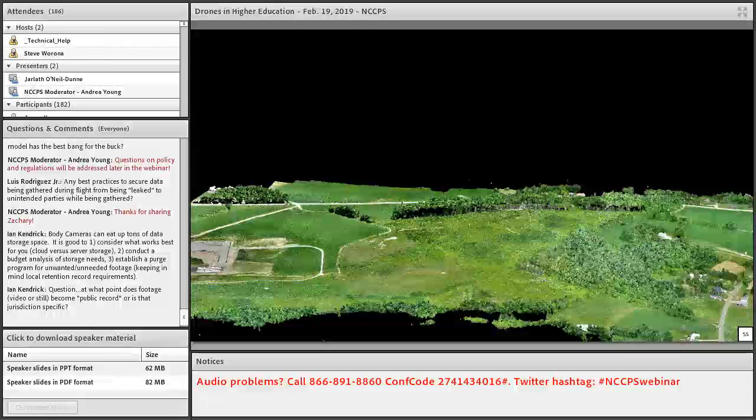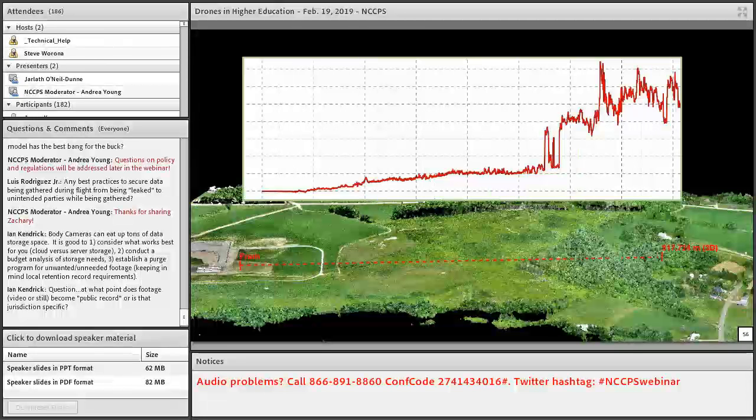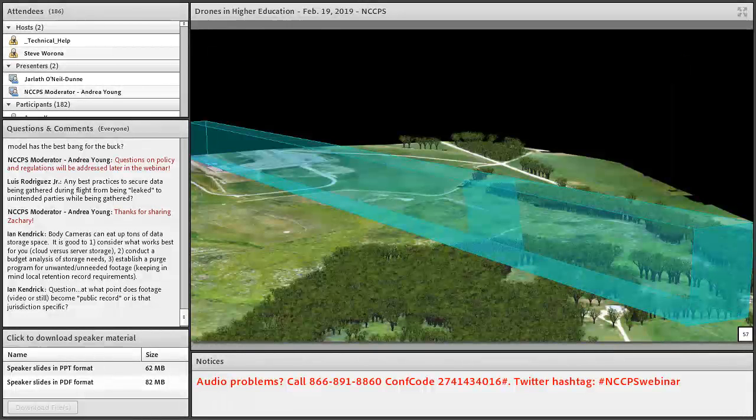Well, you can go out and measure all those trees manually, or you can get out, use your drone, build a 3D model, do those measurements, and then bring it into GIS, where each one of those tree icons there represents a tree extruded by its height from the drone data. And that block that you see there, that light blue colored block there, that's the approach path. So in 3D there, we can see that even though the runway was expanded, the approach path still meets the appropriate FAA clearance, right?